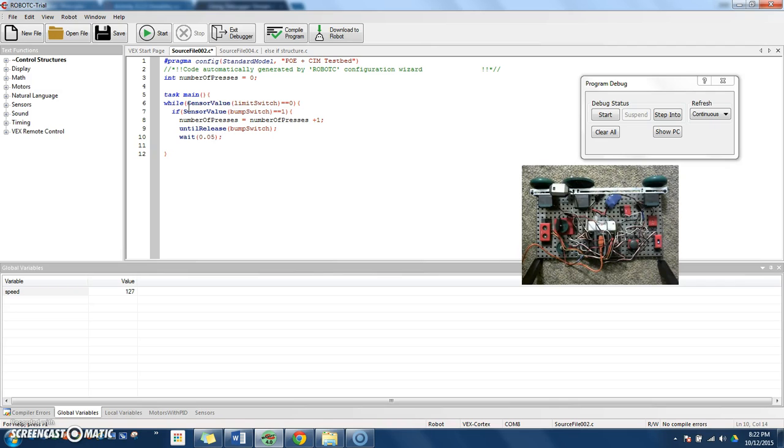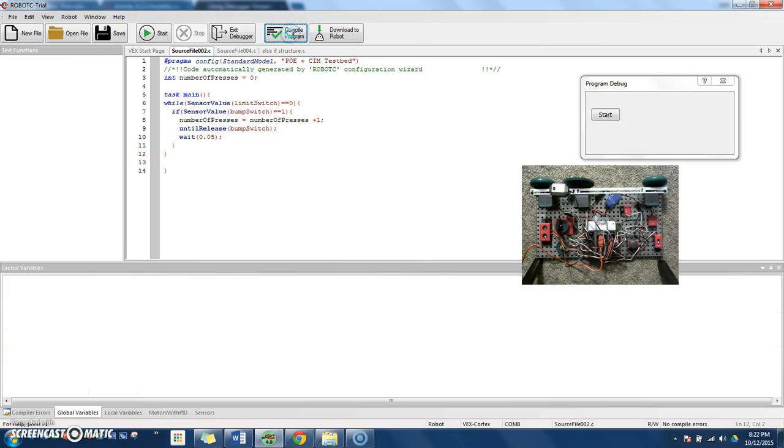And what this will do is it will wait for that bump switch to be completely disengaged or open before it starts reading our values again. Because if it does, then the voltage can jump back and forth inside the button and it can create a ton of numbers. So I'm going to put an end curly brace for my if, and I need one for my while. So we're just going to go ahead and compile this program.